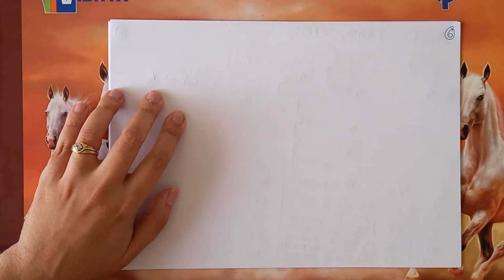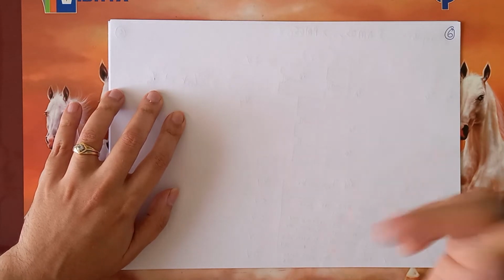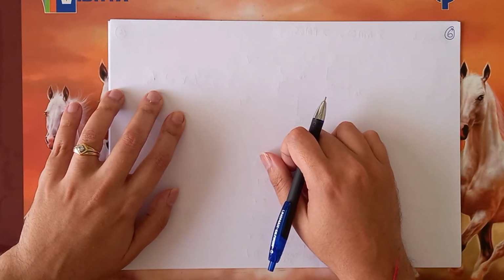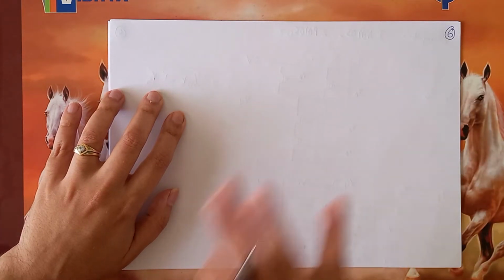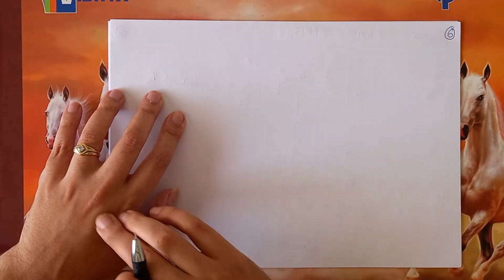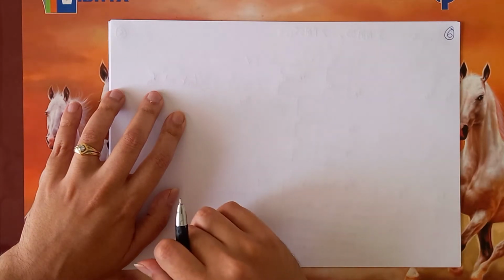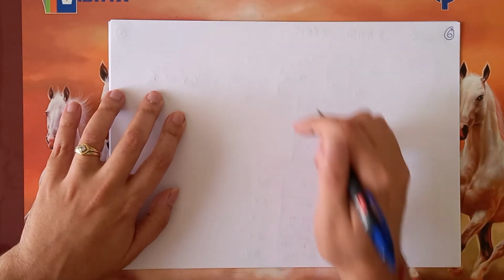Let us look at one more case. Again, we have 2 inputs, so again we will need 2 NMOSes and 2 PMOSes. But now let us reverse that configuration. Earlier we had 2 NMOSes in series and 2 PMOSes in parallel. Now let us do the reverse.